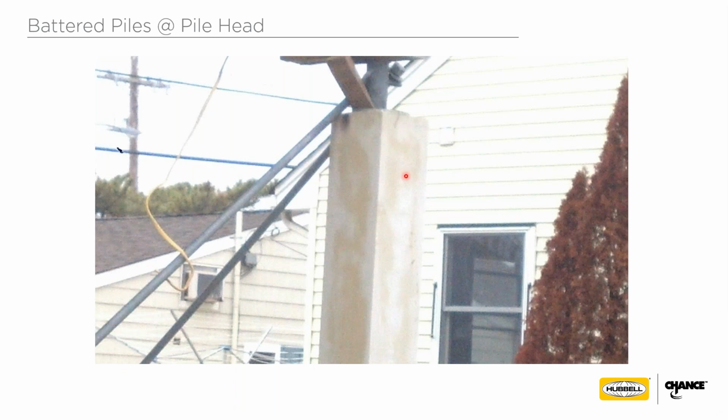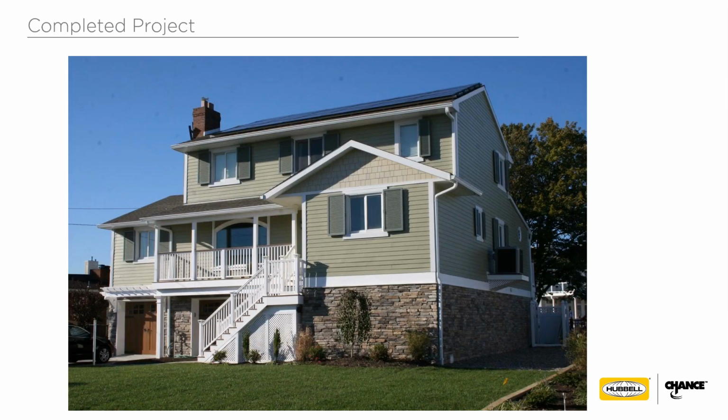This is a decorative square fiberglass column that was used more for the aesthetics, ending up with this type of result for that structure. These are low pressure breakaway panels. So this is truly an open foundation, V-zone type, but obviously it was a very nice result.